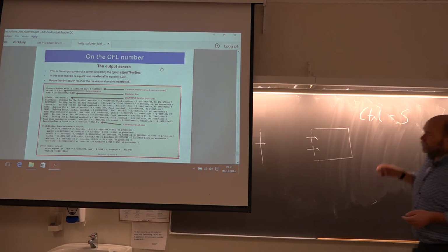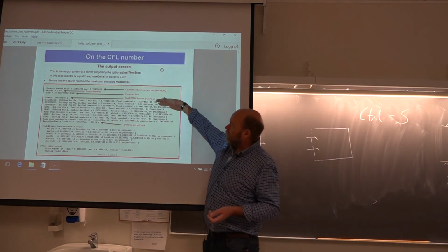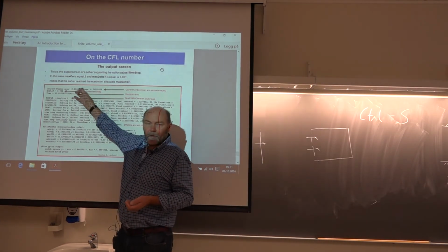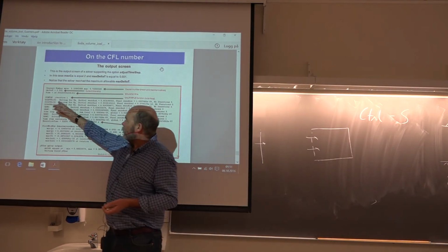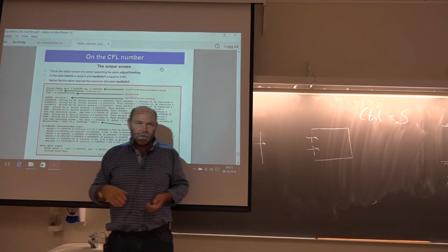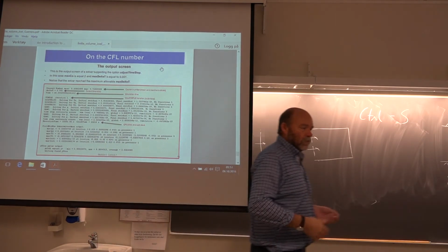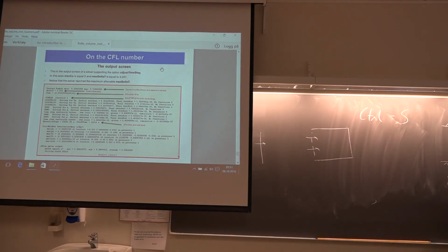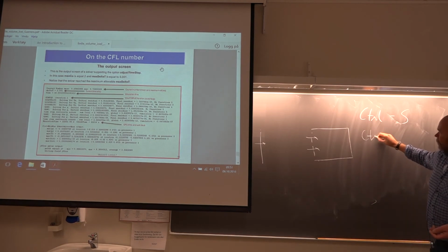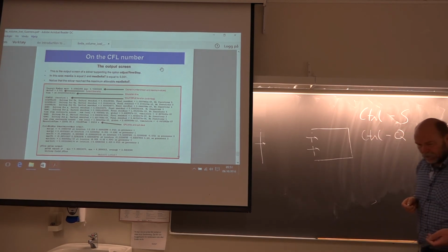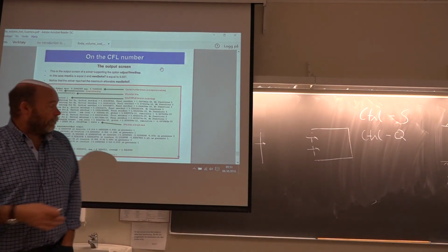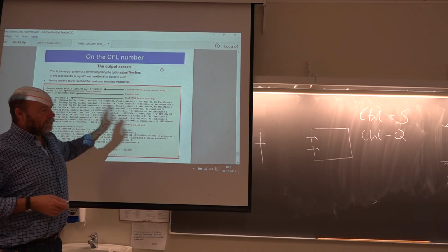But that gives you an option to have a look at all these numbers, especially what the Courant numbers are. Will this go okay? Also, what's my time step now? Is it going smaller and smaller and smaller, or what's happening? So Control S to stop the scrolling. And if everything looks okay and you want to continue, Control Q. So Control S and Control Q are nice to know when you want to stop just the printout on the screen.